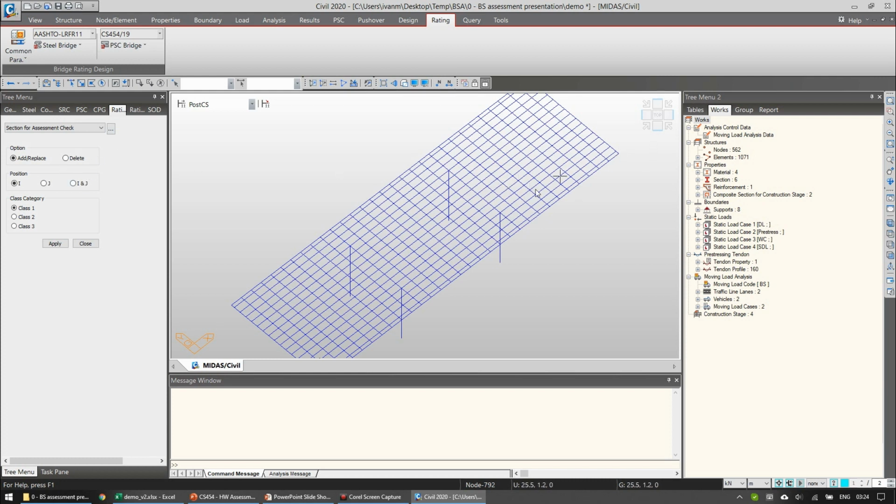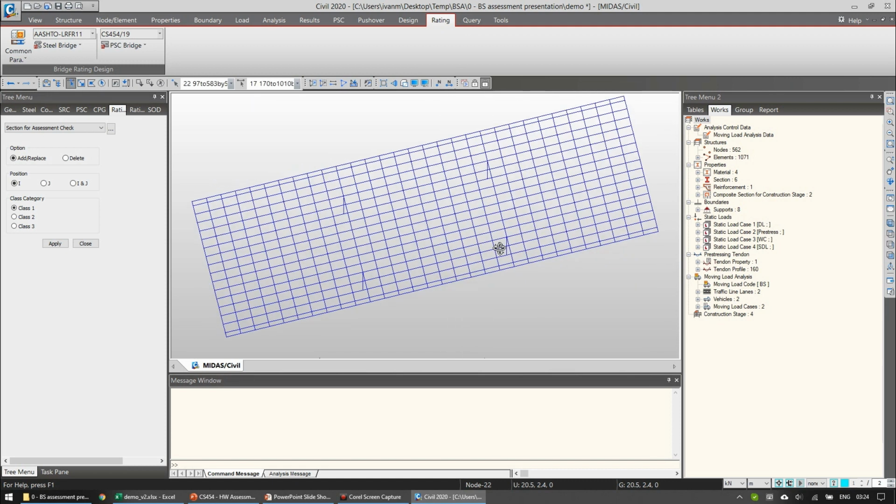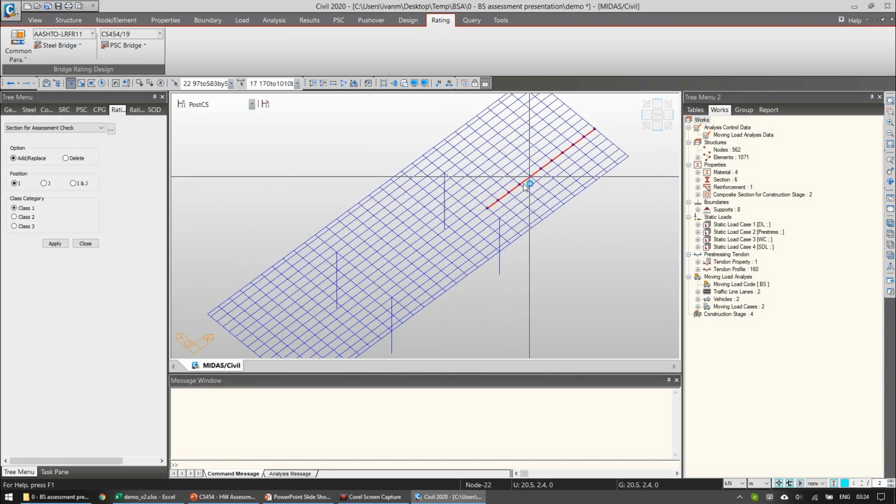So if I choose a set of girders along my structure, let's say I'm going to take that primary here. Let me just see if that's, yes, that is my last span. So after the second pier to the end. And we're going to run the design checks for these elements, section I, which is basically every section across that girder.